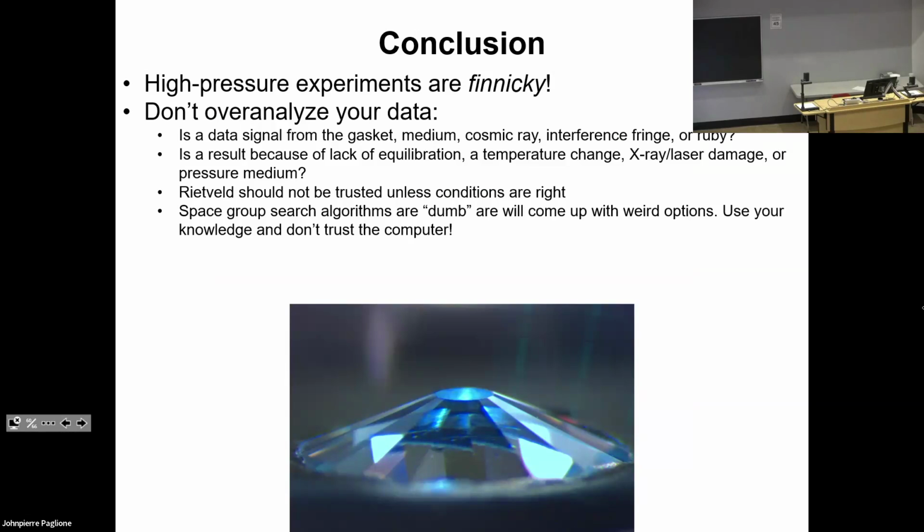And actually, sometimes I worry a lot about my silver paint or whatever it is reacting with the sample. You don't have to worry about that here, other than whatever your lead itself is made out of. There's just so much pressure there that you're getting very good contact, and the contact resistance is usually negligible. But regardless, if you're doing a 4-point measurement, you're getting rid of contact resistance anyway.